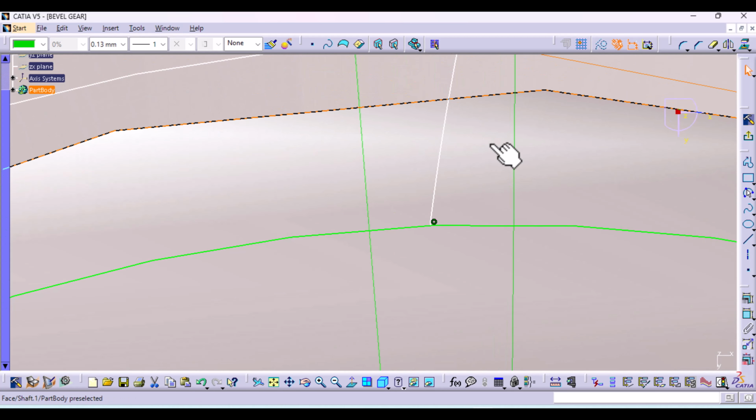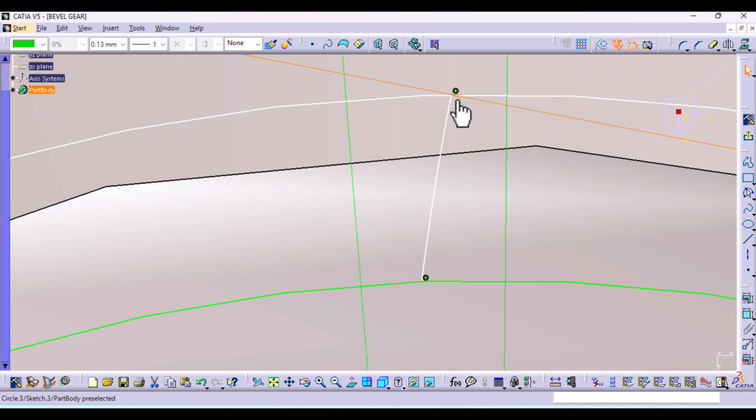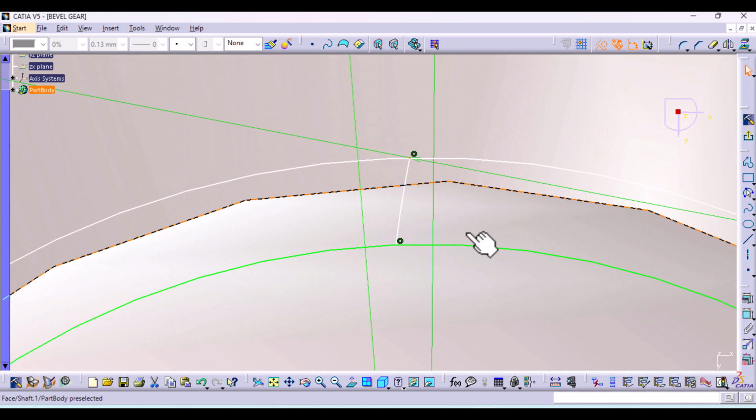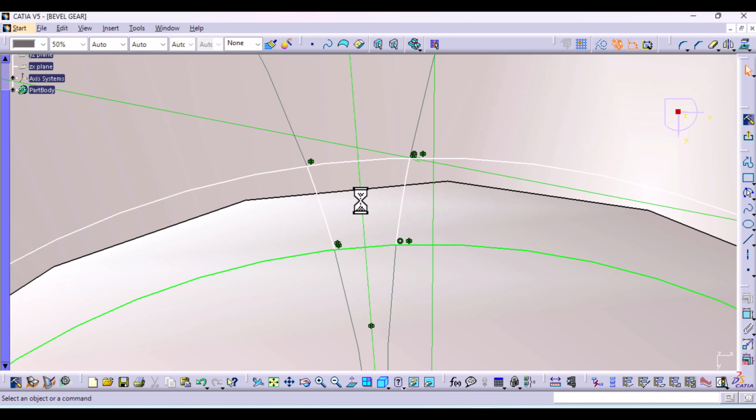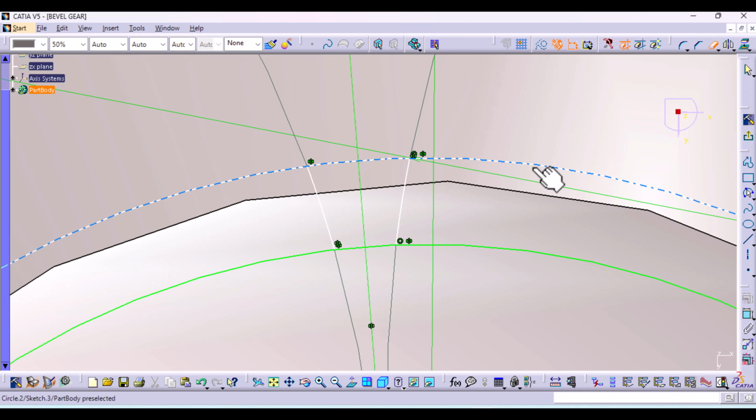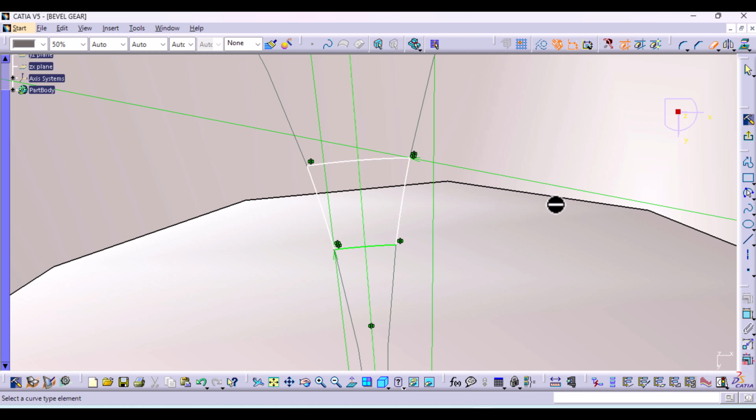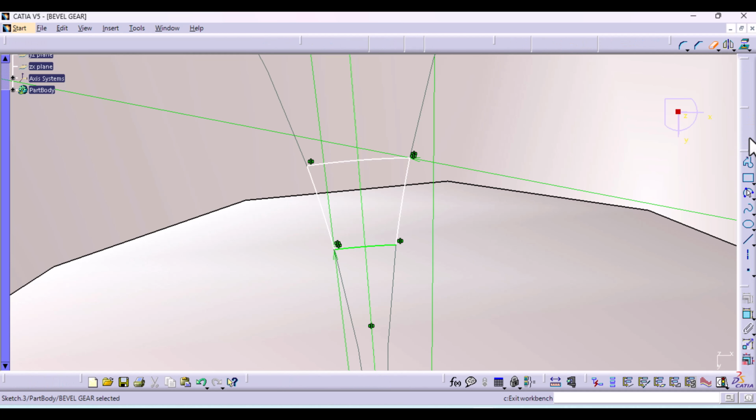So they haven't given us the measurements for how long is the top part, the bottom. So in this case, just make sure the bottom side is bigger than the top side. So now we are not creating the profile of extrusion, we are creating the one for the slot. So I'm going to mirror this using this axis, then select quick trim, trim off the excess circles like that and exit.